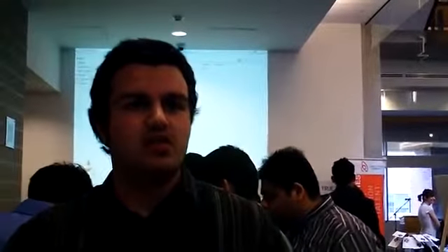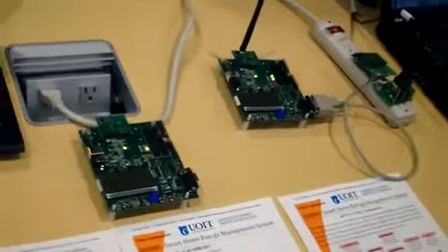Now what that means is, traditionally with GSM or 3G technology, it's always the same star topology. So if you want to send a message from one device to another, you have to communicate to the base tower, and then it would send it to another device. But with a Zigbee end device, it's more like a mesh network. It's kind of like a web. So if I want to send to one end device, there isn't one path. I can send it through multiple routers. If one router goes down, you can use the other one. The coordinator automatically recognizes that router is down, so it would send the data through another path.